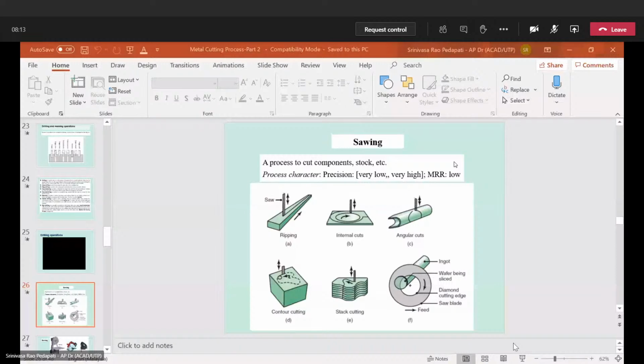Everybody writes turning. Yes, the component given to you has turning, but that turning is taper turning for some part of the part, and taper turning, straight turning, knurling, threading. These are the different operations on that particular component that is given to you. You need to refer to that component, and you have to give the sketch of that particular component. Where is threading happening on that particular component? Where is taper turning happening on that particular component? Like that you have to answer.